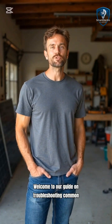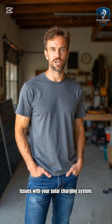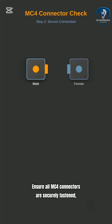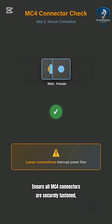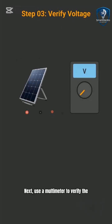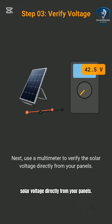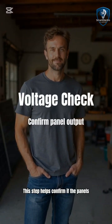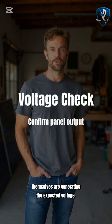Fault: no solar charging. Welcome to our guide on troubleshooting common issues with your solar charging system. If your solar panels aren't producing power, start by checking the DC MCB or miniature circuit breaker. Ensure all MC4 connectors are securely fastened, as loose connections can interrupt the power flow. Next, use a multimeter to verify the solar voltage directly from your panels. This step helps confirm if the panels themselves are generating the expected voltage.